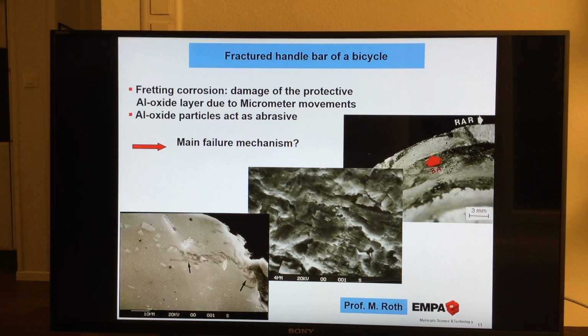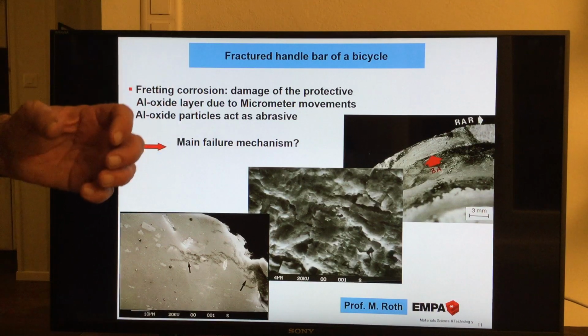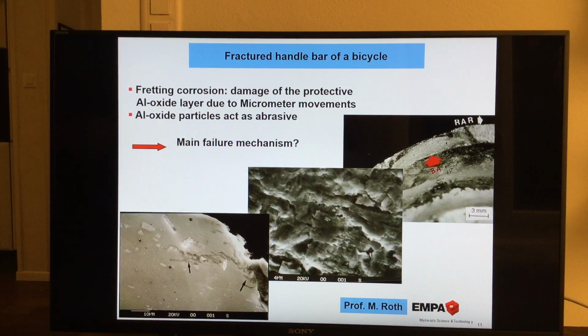And there is one parameter which is very much different between the two materials. Think, when you make a stress-strain curve with these two materials, what do we know about the Young's modulus? Think carefully. The Young's modulus of steel is in the range of 210 gigapascal, and the Young's modulus of aluminium, maybe you remember, is 70 gigapascal. So they have quite a different mechanical behavior, and from this we also will learn how to improve.